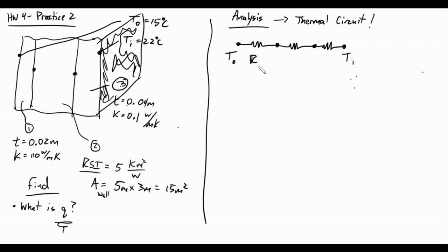So all of these resistances we'll express as the resistance of part 1, and we're running the double prime because these are going to be resistances used to find heat flux. So they're defined with the area term removed from it. And so the equation that will be associated with this is delta T. So the delta T between 2 points is equal to the heat flux that is moving through those points.